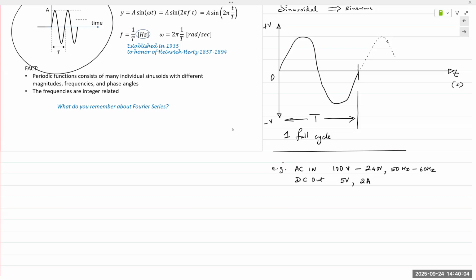So when the first smartphones came out, it was 5 volts and 1 amp, so 5-watt chargers. Then came along tablets with bigger batteries, so they increased the charging speed by increasing the current. And that's where it leads me to the answer to your question. I'm getting around to it. A 10-watt charger for a tablet would be 5 volts and 2 amps. But the USB spec was capped at 5 volts. So if you wanted to charge your devices faster, you've got to supply more power to it.